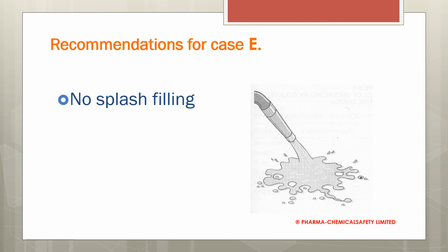Second, you need to find out the limiting oxygen concentration that you need to have inside the reactor. We know that for combustible powders, and I'm using this only for reference, not telling you that it is the right data because it depends on each flammable liquid, normally it is no more than 12%.